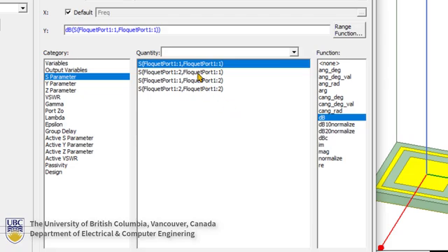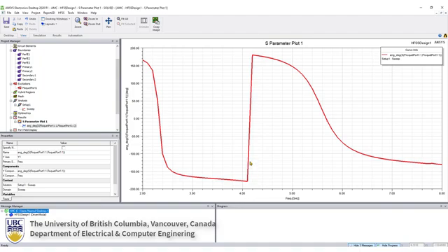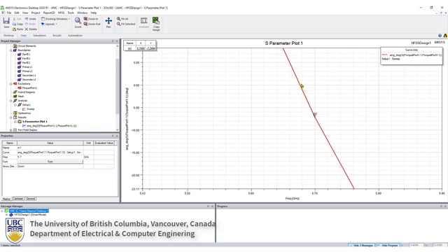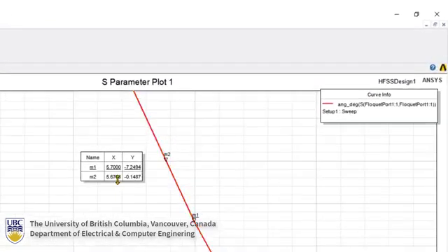So from here I need to see only the transverse electric mode for the time being. Select this one, go to angular degree, and then just report. Here you can see it's very clear that it has an inherent S-shaped curve. We can determine the bandwidth from this plot. For example, if you want to find the resonance, it is exactly this point. You can zoom in and place another marker. Okay, that's fine. So the resonance frequency is 5.6 gigahertz for this AMC.